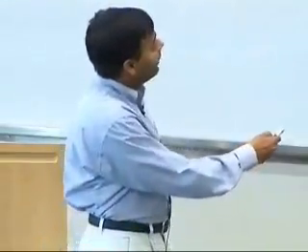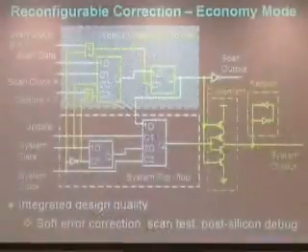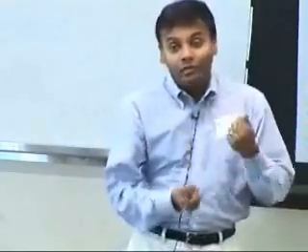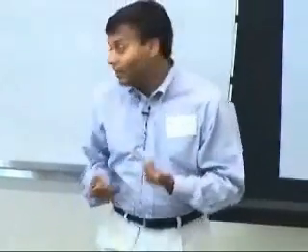And oh, by the way, since you can turn this flip-flop on and off, that means that, again, if you understood your system well enough, you could be in between two modes. You could be in a high reliability mode, and you could be in an economy mode, where yeah, the area you are stuck with, but area is not the biggest deal. The power is the biggest thing, where you can play games either statically or dynamically.